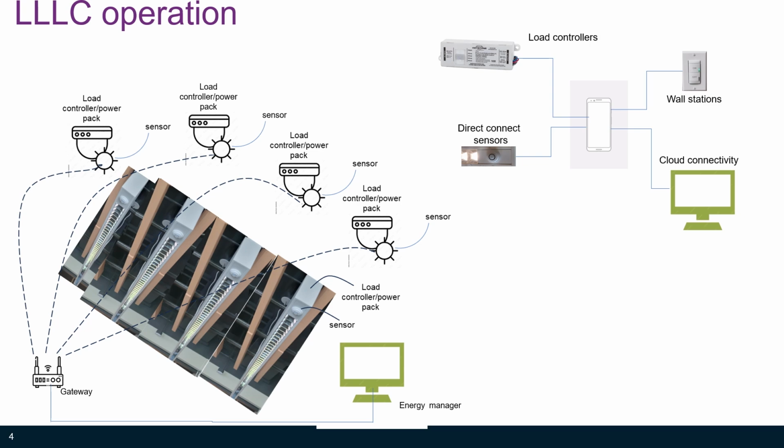The figure on the left of this slide shows the basic luminaire level lighting control. The sensor and controller are embedded in the luminaire, and as seen in the lower right, the communication is sent to each luminaire, each having a ballast or driver with a control unit, controller, and a sensor in each luminaire. The communications are further shown in the figure in the upper right, which can be done via mobile phone or laptop or desktop controls.